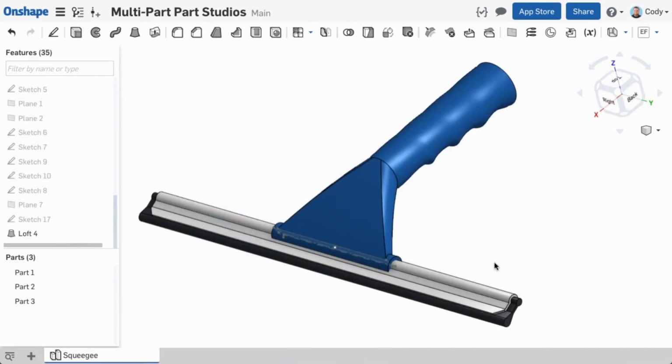One good example of multi-part modeling would be using a part as a tool to be removed from or merged with a finished part at some point in the future. This is a common technique used in other professional 3D CAD systems that is often referred to as multi-body design. Essentially, you're separating a part, making modifications to that separate part that don't affect any other parts, and later merging or removing that part with another.